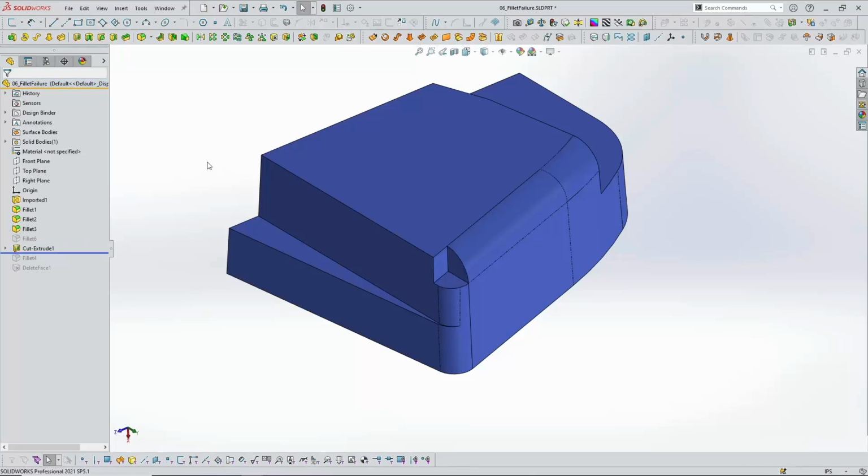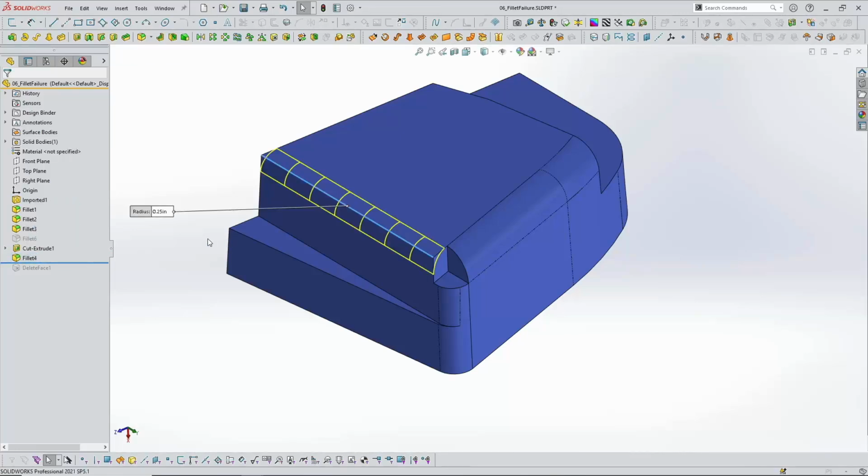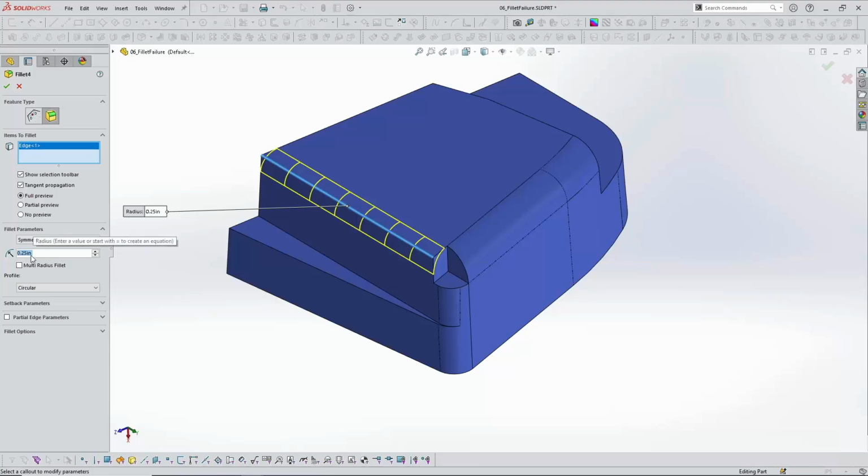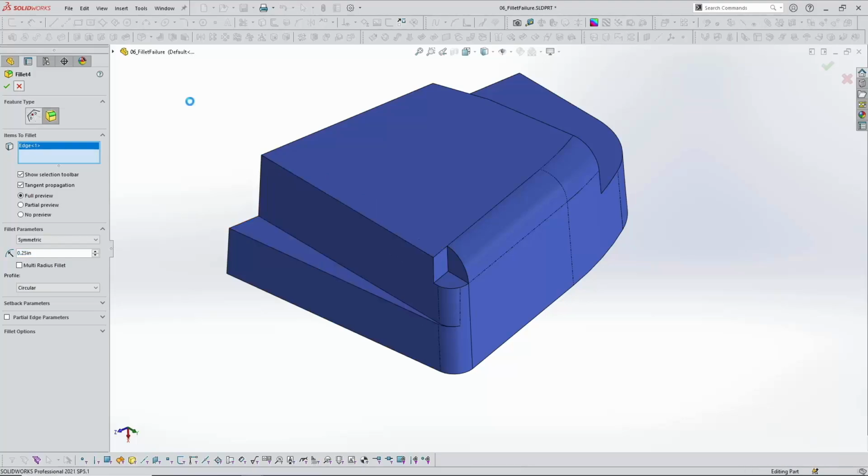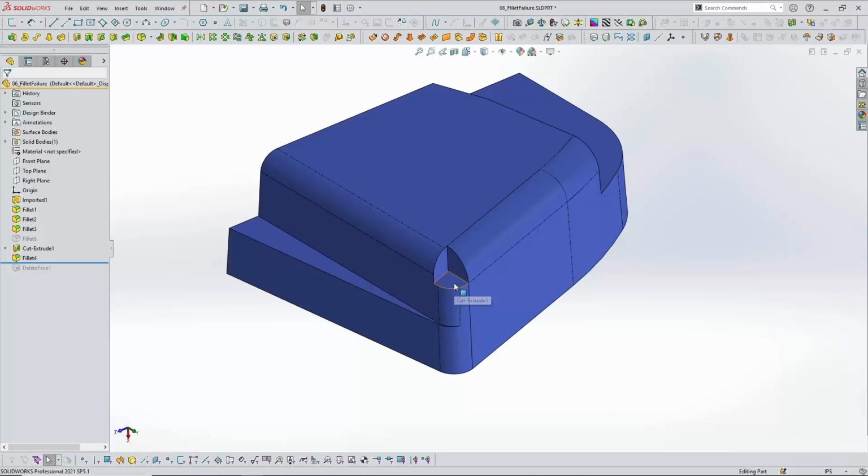And so I'm going to add some new faces to the model. And I did this very rapidly with a cut feature. So I just cut out that corner of the model. And, oh, there's a fillet. Let's check its size. Oh, there's the 1/4 inch. So I'm able to add this by eliminating the corner that the fillet had issues working with. But now I have a notch in my model. How do I get rid of the notch?